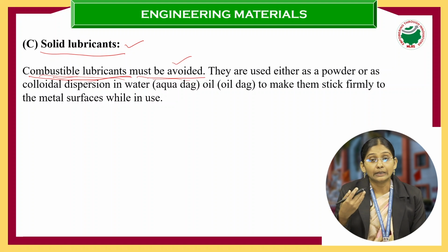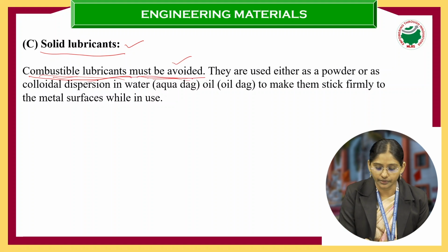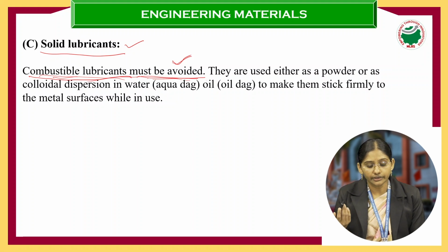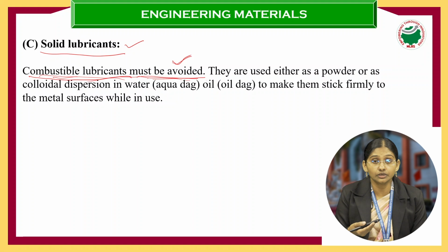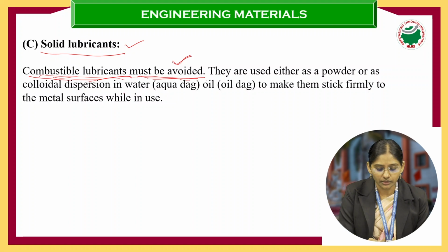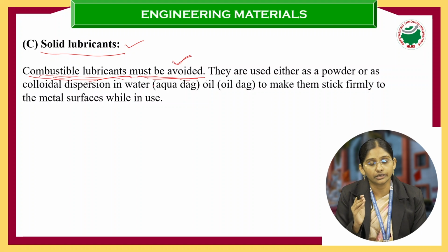So that's why combustible lubricants must be avoided. Now, have you understood? Combustible lubricants must be avoided. So here liquid lubricants may evaporate or may react with the gas and a combustion reaction takes place. And if we use the semi-solid lubricant in these machineries which maintain 1000 degrees centigrade, then what happens? That semi-solid lubricant sometimes converts to liquid. So that also is not advisable. That's why we need to prefer only the solid lubricants.